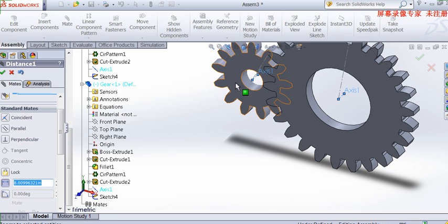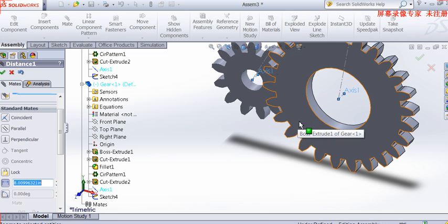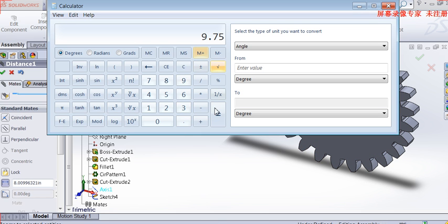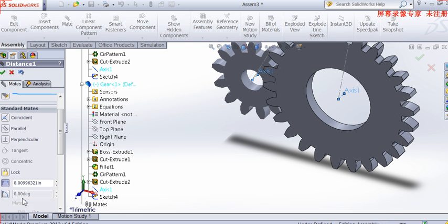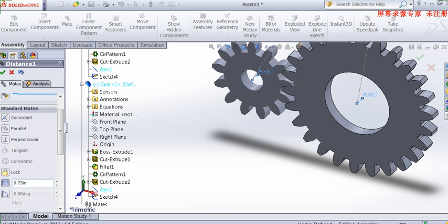The first one, this is N equal to 13, P equal to 2, so the pitch diameter is 6.5. N divided by P, so 26 divided by 2, so 13. So 13 plus 6.5, and divided by 2, 9.75 is the center to center distance. So let's punch in 9.75 here, center to center distance.